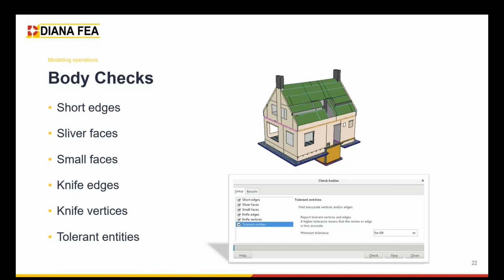One of the main advice we can give you is always when you work with your CAD model, try to make the CAD model as good as possible. So make sure that everything is connected, because at a later stage when you import it to a finite element package, then because of some tolerance issue and so on, you can have some loose part in your model, and it may require some extra work to fix the geometry before you are able to set up your finite element model.